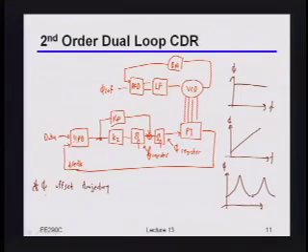Okay, so sometimes you're worried about some spur coming out of your chip. And if it has too much power spectral density, then the FCC gets unhappy or something like that. So sometimes what you'll do is indeed this spread spectrum technique, where you intentionally spread the energy of that clock out over a band of frequencies. Well, if you're going to do that, then indeed your phase is going to have this weird looking behavior on it. And it may even continue and have these weird circles and things like that.